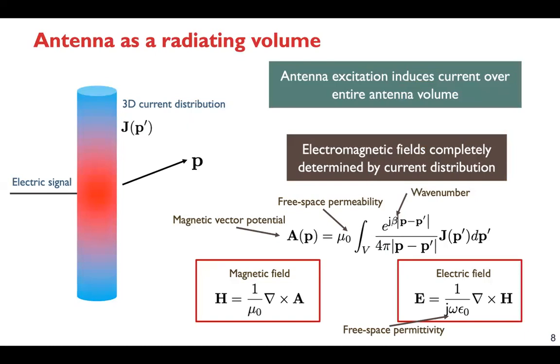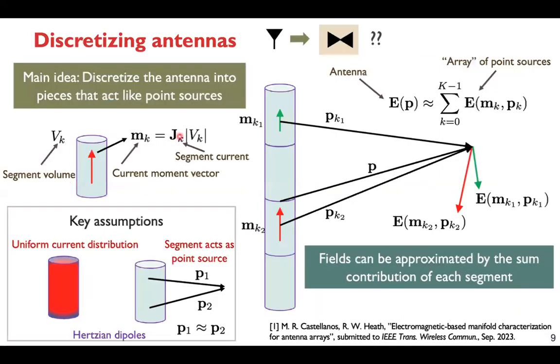But typically, electromagnetic software will discretize the surface into a mesh and obtain a sample of the currents along that surface. And we can actually leverage that to form an array processing kind of framework for the antenna itself. So the way we'll characterize the antenna is in terms of this electromagnetic framework where we discretize the current distribution along that antenna.